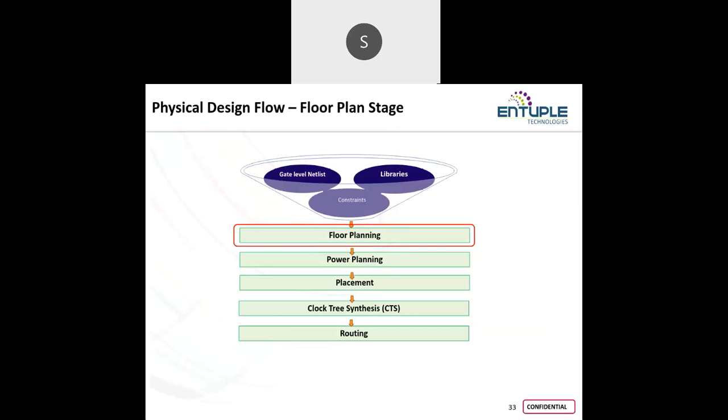To avoid that, you can set the technology node by using the command set design space hyphen process with the technology node. If it is 45, you can mention 45. No need to mention nanometer, you can directly mention the number. So set design space hyphen process, space, the technology node you are using, 90, 45, like that. Once after that, you can start with the floor planning.